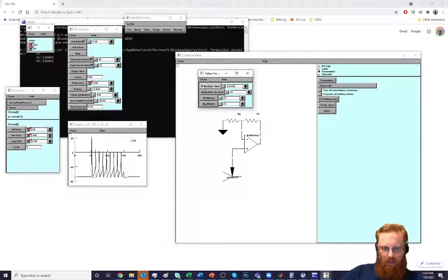Let's just leave that. So we've got the gain on the amplifier, the time constant of the amplifier, which I think is just part of the simulation rather than a real property you'd ever see in a data sheet for an amplifier. But importantly, here are our megaohm resistors here and here. If you're making this amplifier for real, you probably wouldn't use those values, but the point is they're equal, so this is going to be a 2 times amplifier. Yeah, so we can close that.